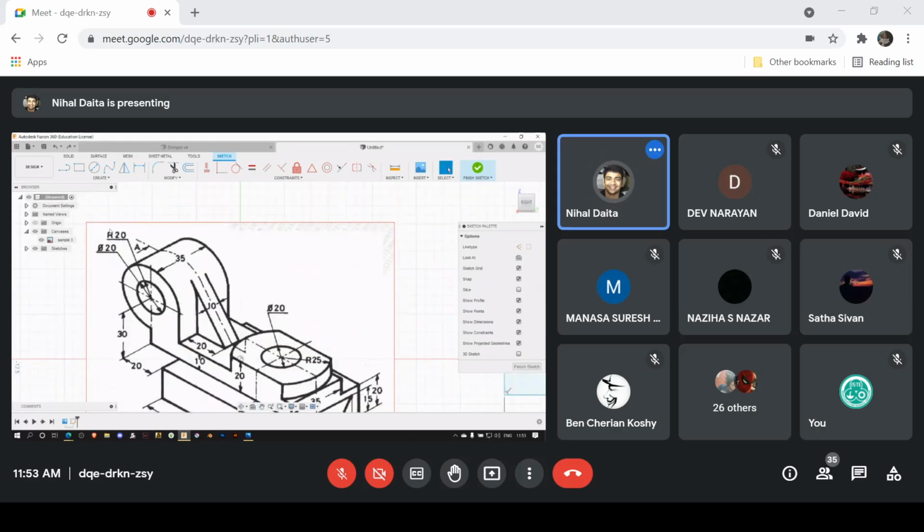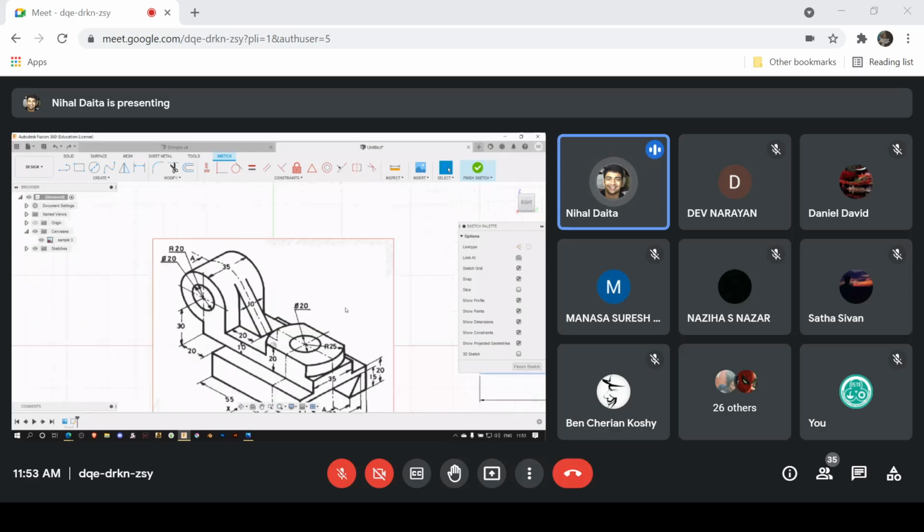So they say it's R20 and Ø20, right? So Ø20 is 20 diameter. So that's referring to this particular smaller circle, and R20. So R20 is radius 20. So that's like diameter 40. So they'll usually refer to the outer one. The dimensioning is not perfect, but it's fine.